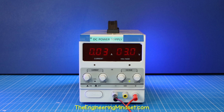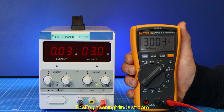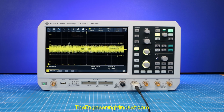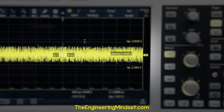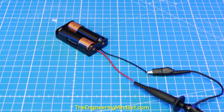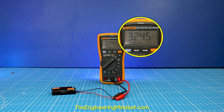This power supply says it's providing 3 volts. This multimeter confirms that, but this oscilloscope shows that's not quite true. It's a terrible 3 volts. For comparison, this 3-volt battery pack provides this clean, constant voltage signal, but it's also not 3 volts.